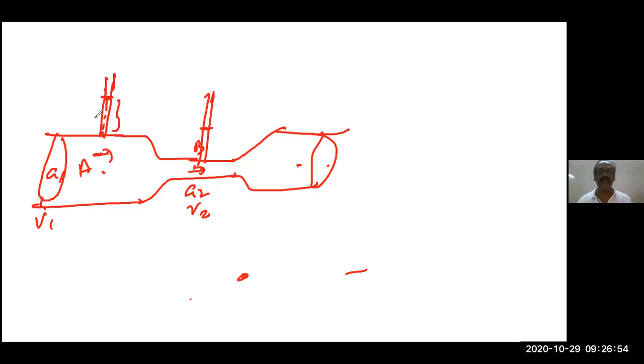If you measure this height, that will give you H rho G, height, density, gravity, the pressure of this column. That pressure is exerted from here. So this height difference will give it. Here this much water can be lifted, and here this much. The difference in height between this is X, this is Y. X minus Y will give you H. So H rho G will give you the pressure difference of these two points. Clear? Yes. Once we can calculate the pressure difference, there is a formula here.